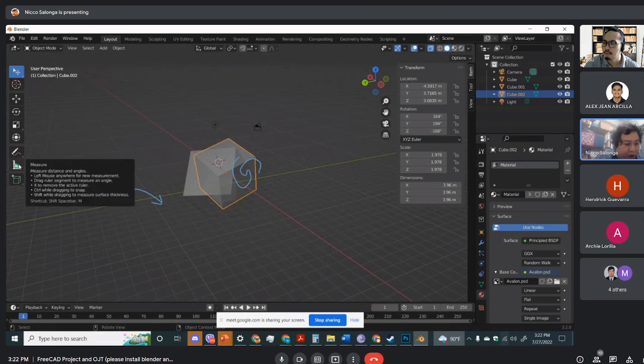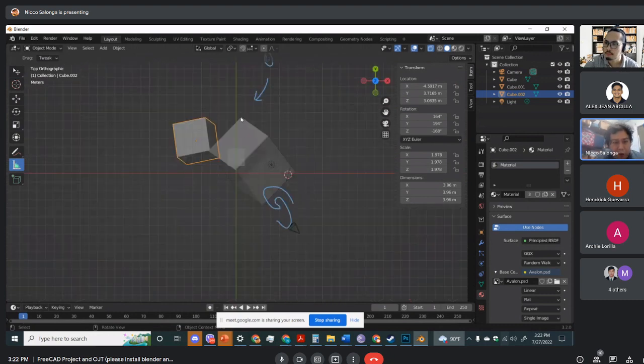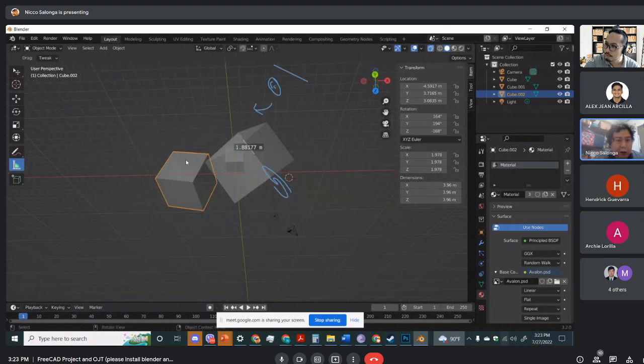Now, the measuring tool lets you measure what you're working on. It actually has instructions when you hover on it. But anyway, it's usually easy to measure when you're doing it here, like, in a line. You could press Control to kind of snap it to things. It's going to be useful for the design, for dimensions. And you could also, what do you call that?